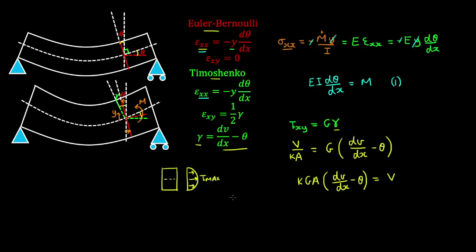But recall that our sign convention was positive. We had a shear couple acting as follows, and sagging moments on the cross section. So this shear couple would distort the section as follows, which basically causes a clockwise shear deformation.